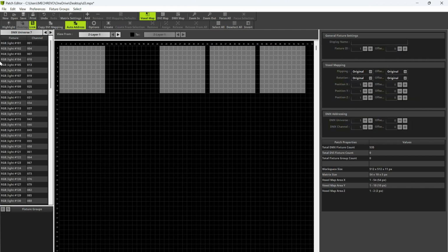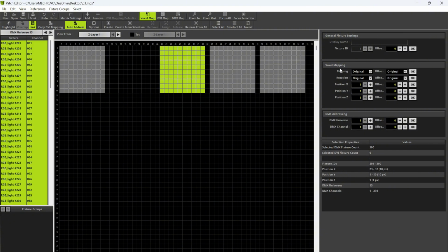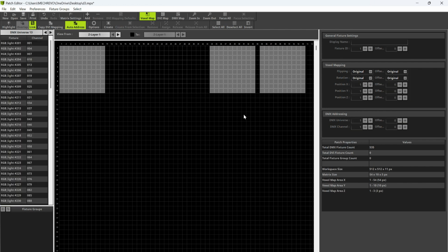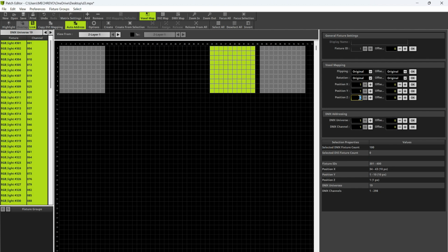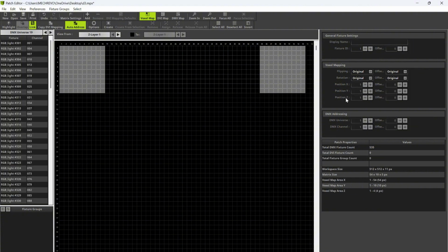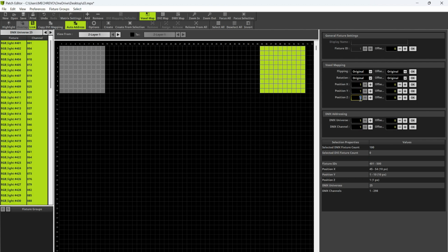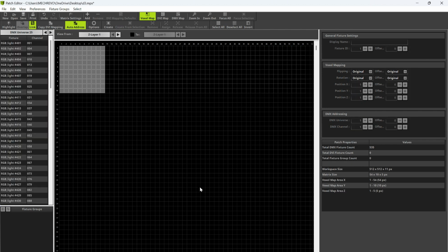Then you do the next one. Make sure you don't mark anything here. You click to unmark everything, then do the same thing, Control Shift, and we mark what we want, and here we change to 3, then OK, and mark here, then we do the next one like this until we are done with our mapping. So now we're done with our mapping.